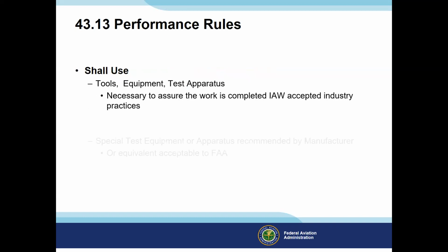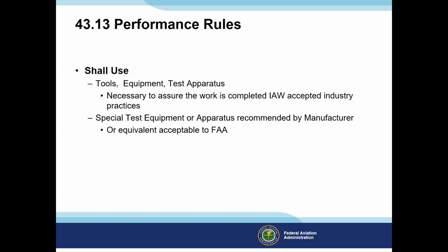They shall use tools, equipment, and test apparatus necessary to ensure the work is completed in accordance with acceptable industry practices. You have to have the right tool for the job. Special test equipment or apparatus recommended by the manufacturer must be equivalent and acceptable to the FAA. So you may not have the latest, greatest, but it has to be equivalent or acceptable.